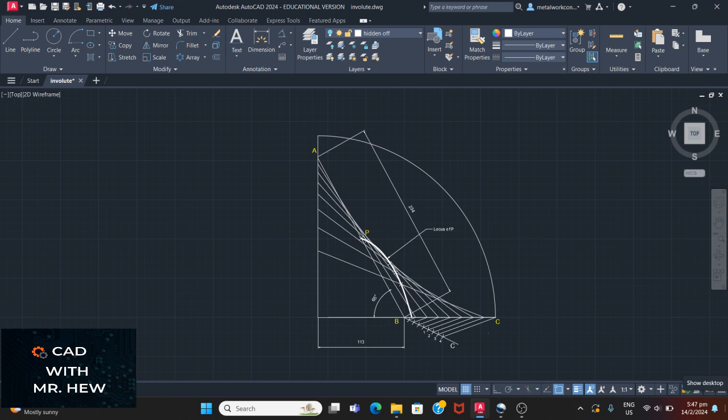Right, so we have plotted the first movement of B from B to 1, right? Which will be right there, right? And then from this point, we mark an arc to intersect the vertical line, and then where the arc or the circle intersects the vertical line, that is where A would move to, okay? We're going to repeat the process, okay? All right, the ladder has now moved to the second point, so we're going to join from where the arc intersects the wall to the second division. Enter, right? Is that clear? All right. And we're going to repeat the process until the ladder is flat.